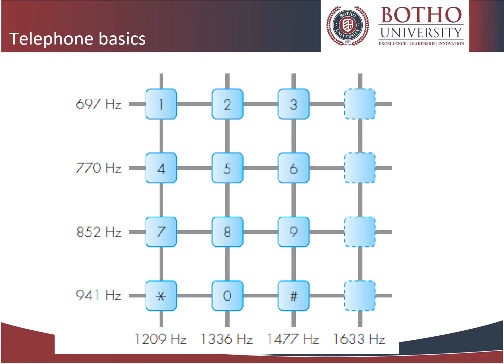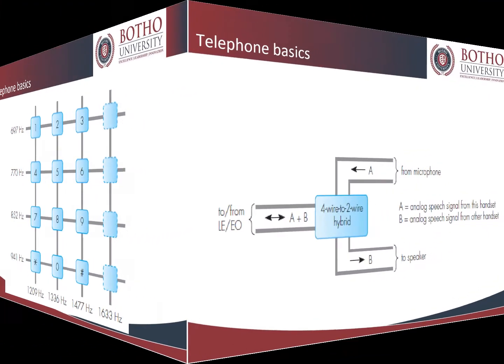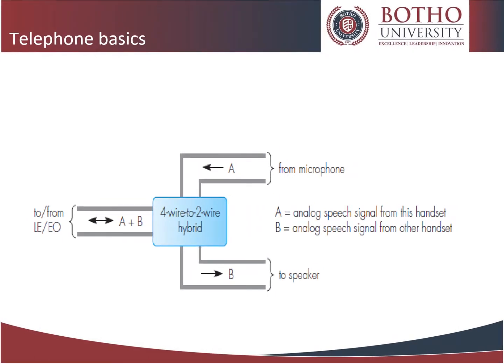The called number is then passed to the exchange control processor. Then it proceeds to initiate the setting up of a connection through the switching network to the called party. The ringer circuit is connected across the subscriber line to alert the called subscriber of an incoming call. The LTU of the called party applies a series of short bursts of a pair of low-frequency ringing tones to the line. The lifting of the handset by the called subscriber causes a current to flow as before and, in response, the LTU removes the ringing tone. Both subscribers are aware of this, and the conversation then starts.